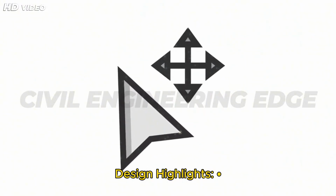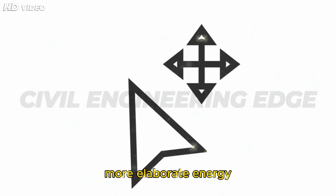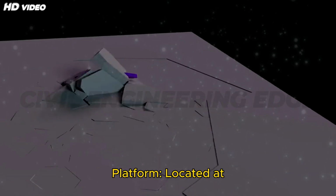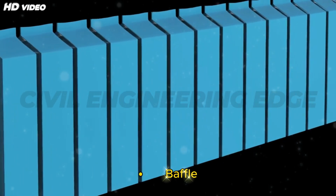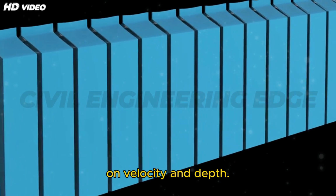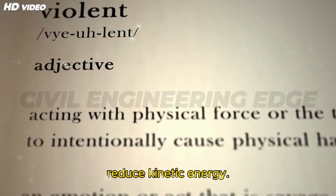Design highlights. Crest and glacis: similar to the straight glacis fall, but followed by a more elaborate energy dissipation system. Baffle platform, located at sequent depth D. This platform supports the baffle blocks. Baffle blocks, placed in rows and sized based on velocity and depth. Their function is to increase turbulence and reduce kinetic energy.